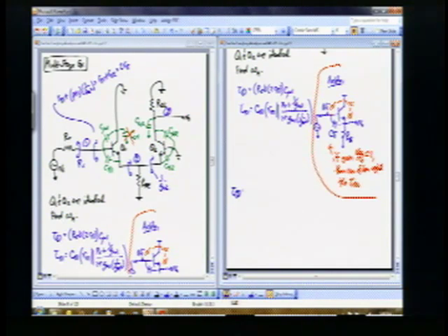Exactly. So there's C pi 2, but what's C pi 2 doing? Is it a difficult capacitor like what we had? No, it's going to ground. Yeah, it's going straight to ground right there. This gate is grounded here, so C pi 2 shows up there, and now it's got to be multiplied by the driving point resistance in shunt with node 2. What is that resistance? Someone tell me?